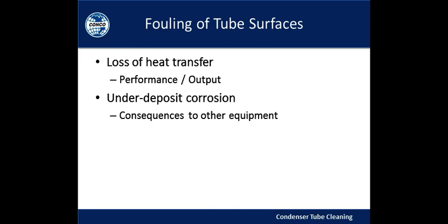Well, let me give you an example of common conference references. One fellow says, you know, we track our boiler tube failures, and don't you know it, they come almost to the day 6 months after a condenser tube failure. Well, look, if the contaminants penetrate the tube wall and get into the condensate, they will go to the boiler. Consequently, they may also go up to the turbine.